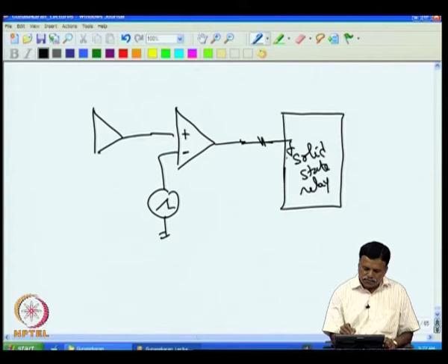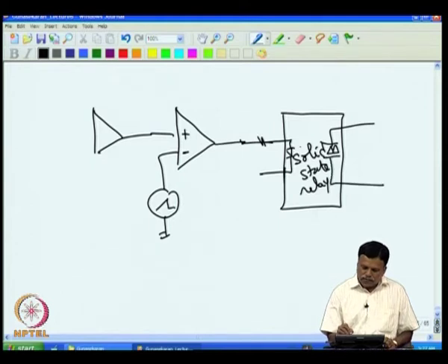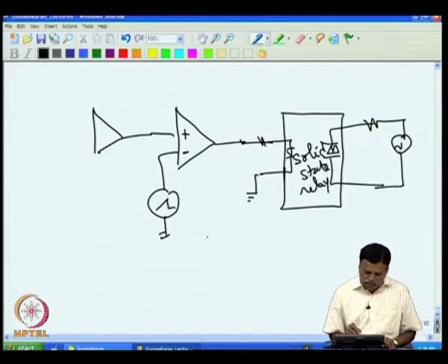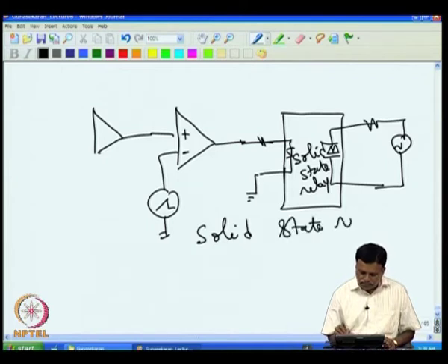Then in the other side you have this thyristor connected inside and all the firing circuit also built in. All that you need to do is connect this. So life is a little easier, one need not struggle, and you get isolation and firing circuit, everything. Whenever this is high, this will be on, and whenever this is 0, it is off, and also solid state relay with zero crossing is available. So you can buy a solid state relay with zero crossing.